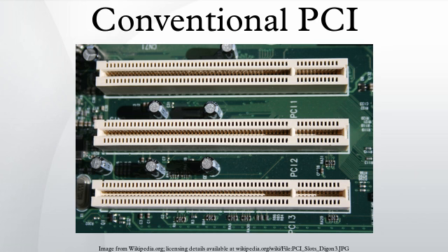Merging: multiple writes to disjoint portions of the same word may be merged into a single write with multiple byte enables asserted. In this case, writes that were presented to the bus bridge in a particular order are merged so they occur at the same time when forwarded. Collapsing: multiple writes to the same byte or bytes may not be combined, for example, by performing only the second write and skipping the first write that was overwritten. This is because the PCI specification permits writes to have side effects.